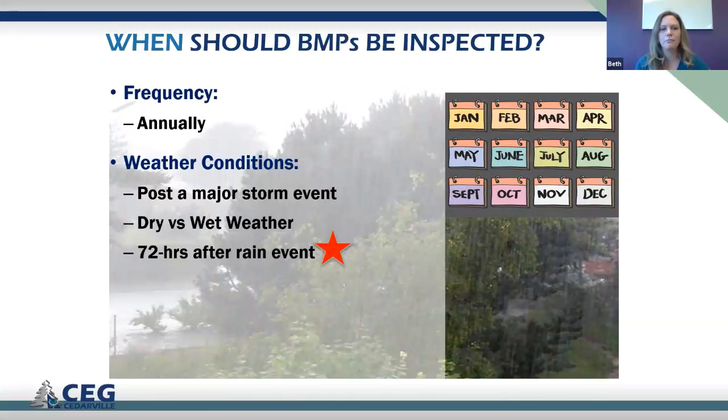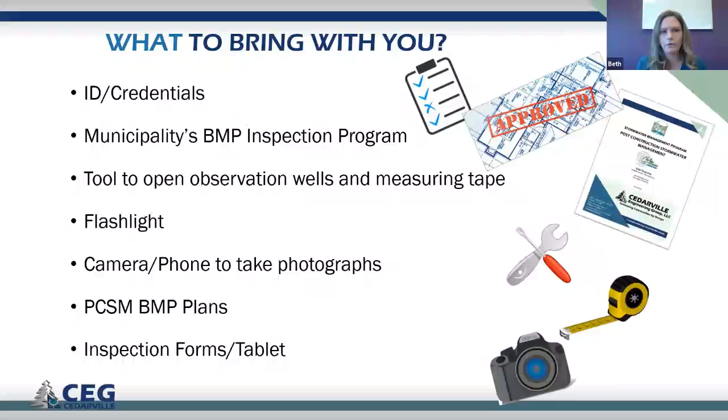And then weather conditions in terms of when you should conduct the inspection. It's always good to conduct an inspection after a major rain event to see how the system is functioning. It's also good to consider looking at the BMP during dry weather versus wet weather. However, if you're just doing one inspection a year, most BMPs are designed to fully dewater. Now that's most, not all, within a 72-hour period after a rain event. So that is probably your best bet in terms of conducting your inspection to make sure that it's functioning properly.